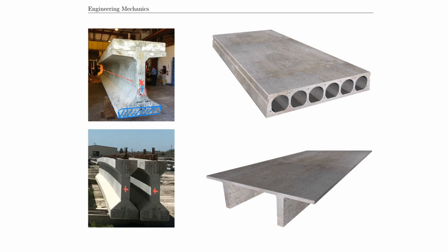For the concrete slab here, the hollow slab is the same, so there was a centroid location right there. And what's the trick here? Same thing, the material here in the middle is not really helping. Remember that if the beam smiles, you have compression on the top, tension on the bottom, and so the material in the middle does not really resist that tension or compression, and so you don't really need it. And this is true for all these pictures here.